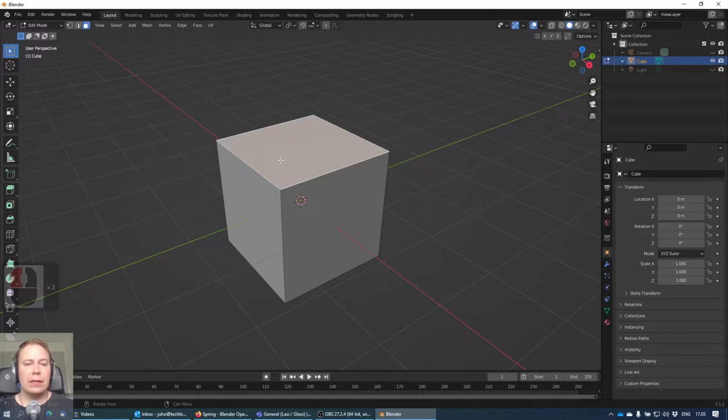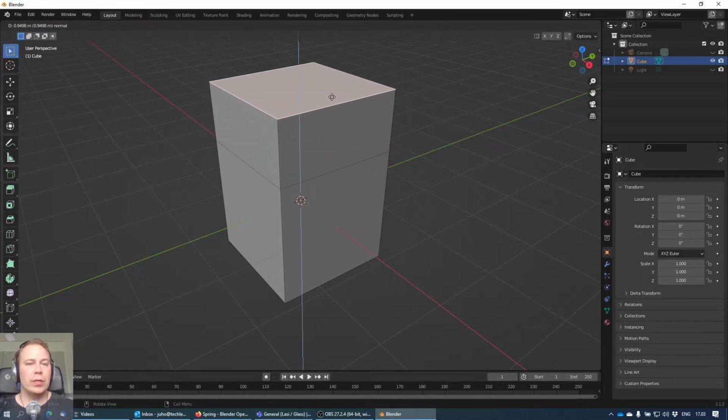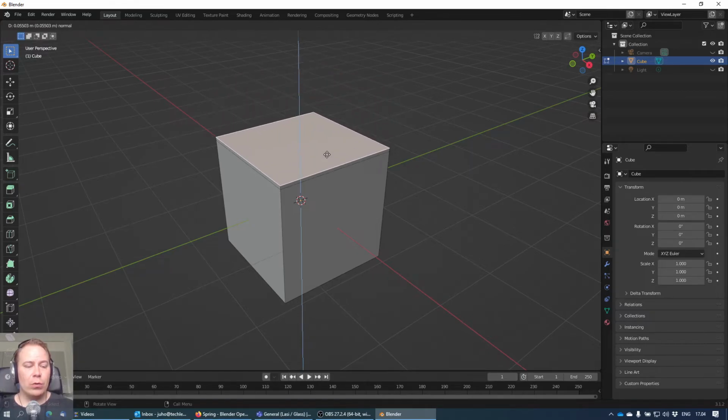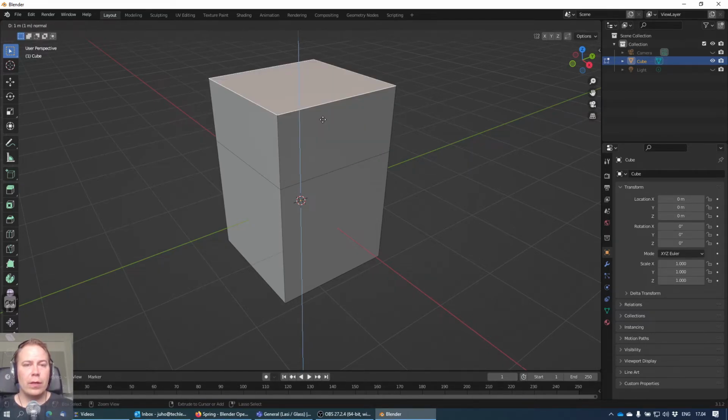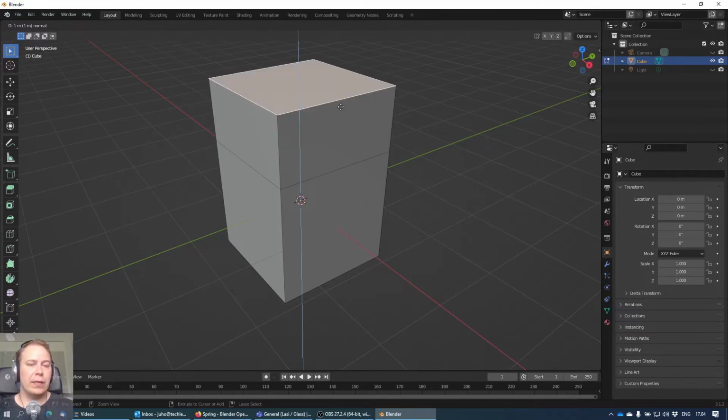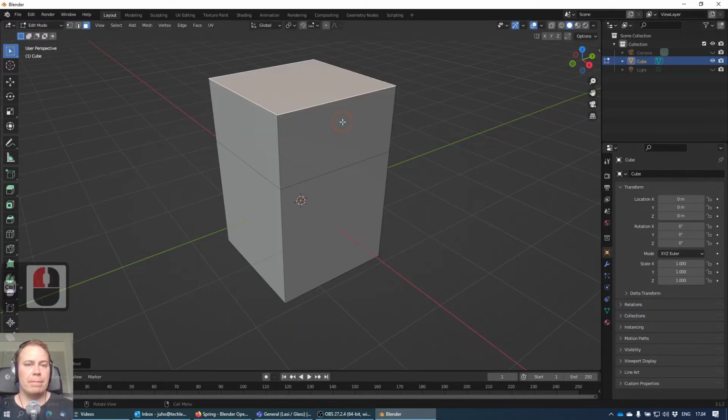Left click on top of the cube so that it becomes active. And then when it's active, press E, which equals extrude. So it's going to extrude the actual face from the cube. When you hold Control, you can use steps in order to extrude a certain amount. So let's extrude it half. So by holding Control down, and then pull it up.